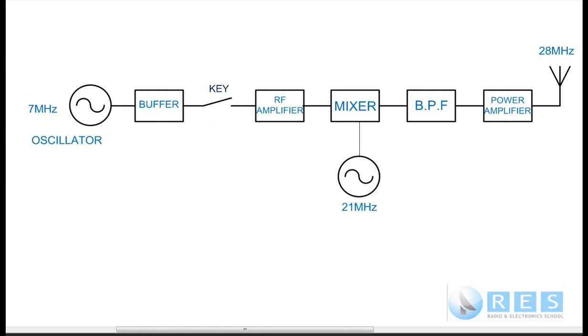Even though we're not doing transmitters in this tutorial, I thought that this would be an opportune time to bring some of these oscillators and amplifiers together and show you the block diagram of a Morse code transmitter. It will just help fit it together and hopefully help you remember it all. A Morse code transmitter just transmits a carrier wave, a sine wave, at radio frequencies on and off.